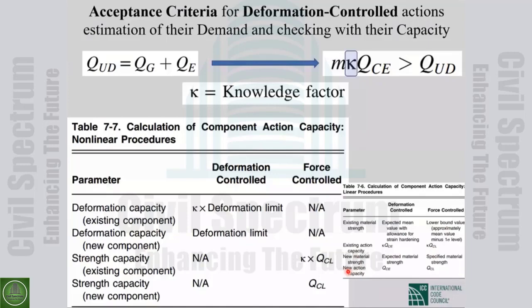The same holds for our talk on Tuesday for the nonlinear procedures. Again, the kappa applies to existing components: to the deformation limit of the existing component, or, for the force control ones, to the lower bound capacity of the force control element.